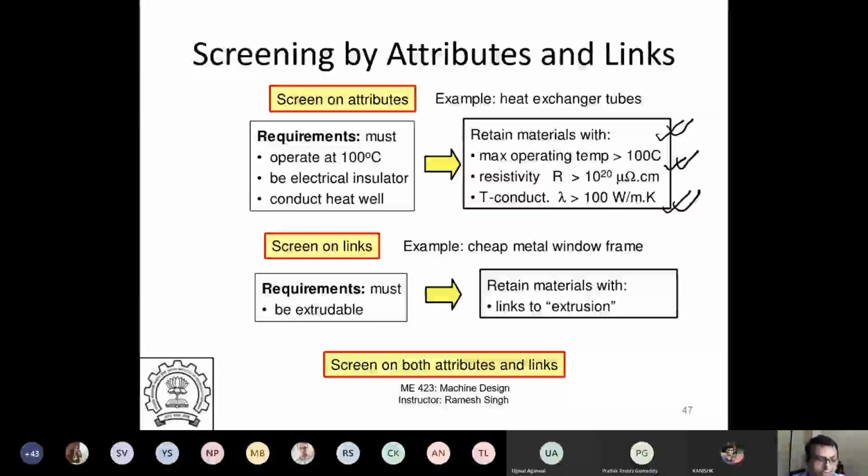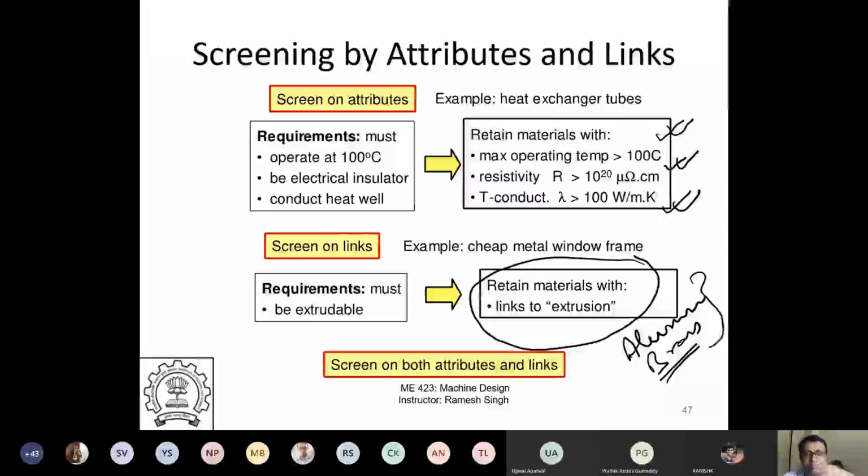So you will basically say we would use materials which can be extruded. Extruded materials typically are softer materials. So aluminum, brass, these will be extruded, but then you choose the cheaper one, because steels typically are difficult to extrude. Not that you don't get extrusions in steels also, but you can get very nice shapes in aluminum where you will get a reasonable amount of stiffness at a much lower price. So they will actually have these nice extruded sections, which are reasonably stiff.